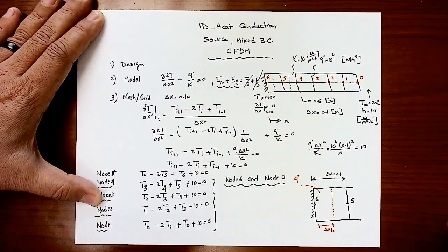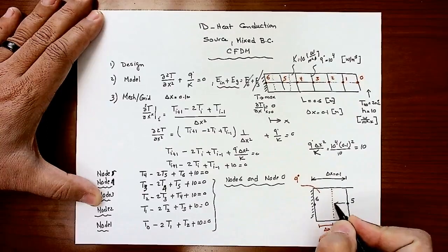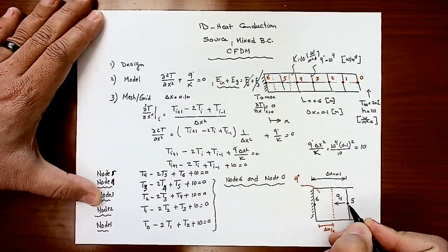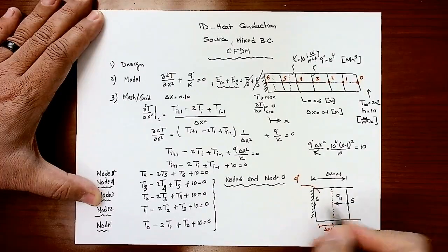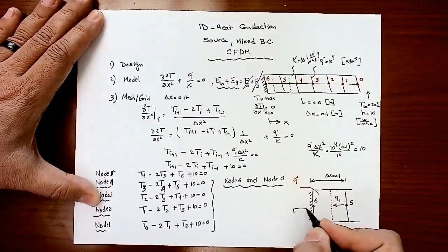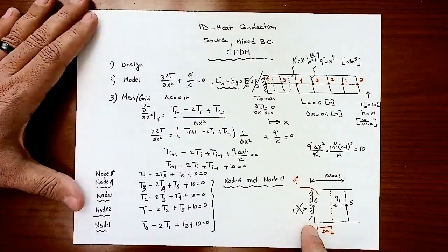Now let's look at the energy. According to the energy balance method, all the energy has to be coming in. So I'm assuming that I'm going to receive part of that Q because of the temperature difference between node 5 and 6. But because that face is fully insulated, there is no heat in or out, right? According to the energy balance, I should have Q in, but this will be 0 because the surface is not allowing any energy to be received.